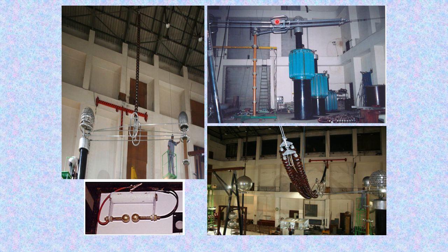You can see here the corona control rings, the end fittings, the metallic yoke plate and other things, all the accessories similar to the tower configuration where the insulators are strung. This is done in the laboratory, and using the sphere gap arrangement we connect across each insulator disc, and the voltage is applied. The 5 readings of the breakdowns across the sphere gap are taken.